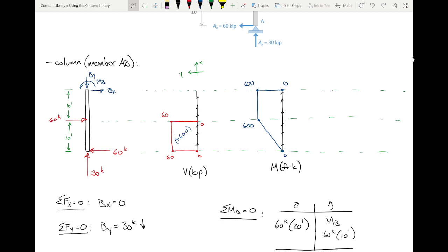And the way that a lot of structural analysis packages will work is they will construct the internal diagrams based on the order that you drew it. So the way that Mastan or RISA or all these packages work is that you create what are called nodes and elements, N-O-D-E-S and elements. And so if this is node 1 and this is node 2, it'll draw it from node 1 to node 2. And so it'll draw it like this. But if you order it the other way, if this is node 4 and this is node 7, it'll draw it that way. It goes in order. Okay, so whatever way you wrote it.